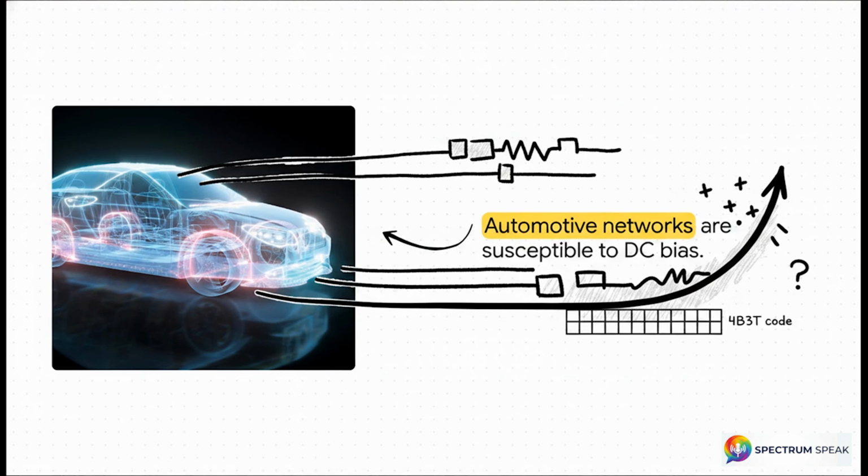Picture the thousands of microcontrollers firing off inside a modern car. We send ones and zeros using electrical voltage. But there's a trap here. If you send too many positive voltage pulses in a row, this unmanaged DC voltage component, what engineers call the Gleichspannungsanteil, starts building up on the wire. Your baseline voltage literally drifts away from zero. It distorts the signal so badly that the receiver eventually can't tell a 1 from a 0 anymore.